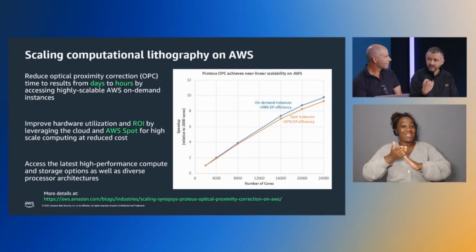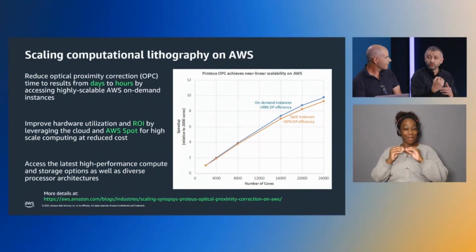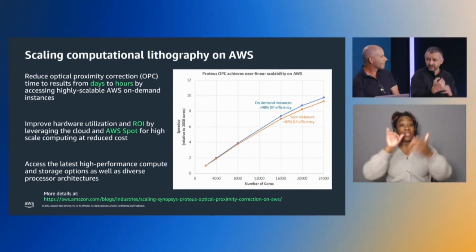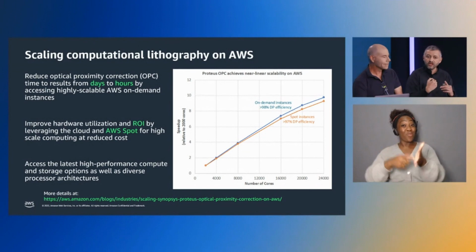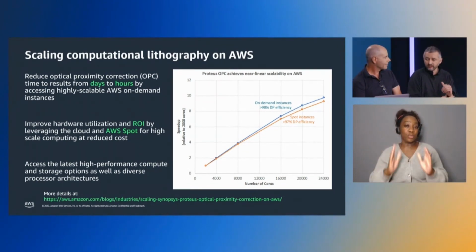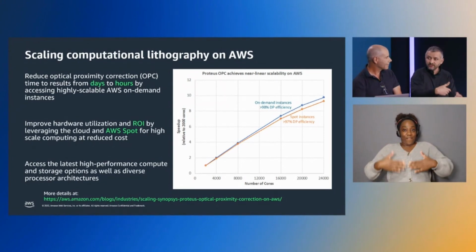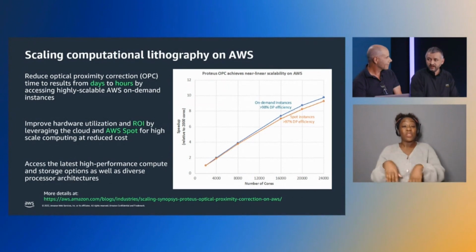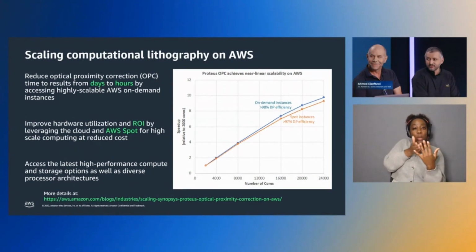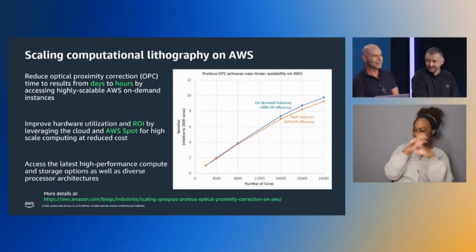So now imagine the chip that we were talking about. This typically has maybe 15 to 20 different layers, and you need to do this process for each one of these layers. I'm talking about the layers that are actually exposed to the end user, that is running or creating the physical layout. The foundry puts additional layers in between behind the scenes, but let's just ignore these. I'm just talking about the typical layers that are exposed to the designer. It's already complex. Yeah, exactly. It's crazy complex, right?